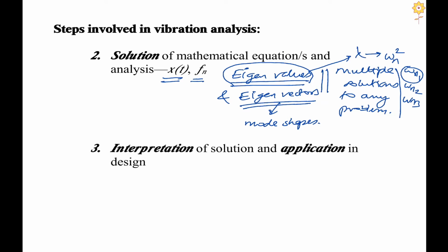Now, the last step is also very important. Based on the output that we have got, we have to interpret the solution, right. Whether or not these values obtained after solution are acceptable to me or not. I may have a lot of deformations of the elastic members, which may not be practically feasible. So, deformation is one of the criteria of failure, and to select whether the design is good or bad. So, I need to talk with respect to deformations. The other one is that because of deformations I am having stresses induced. If the stresses go beyond the permissible stress for the material, then also I can say that the material is failing. So, I am having these two failure criteria, right.